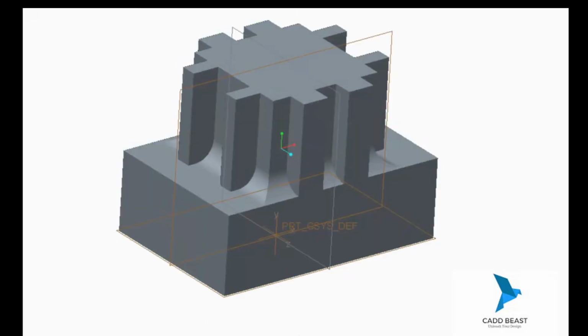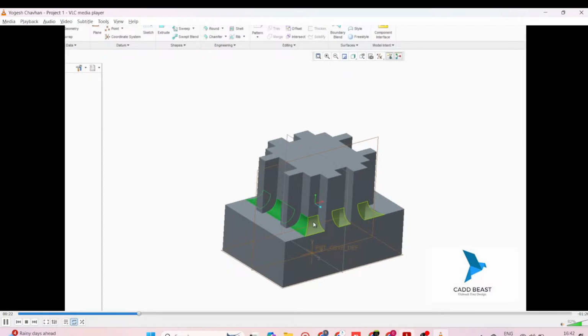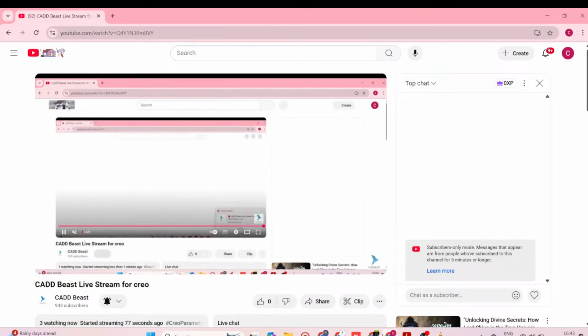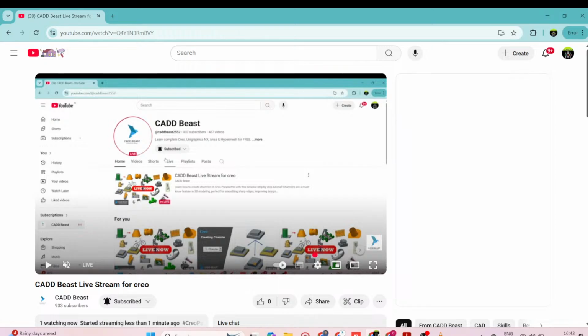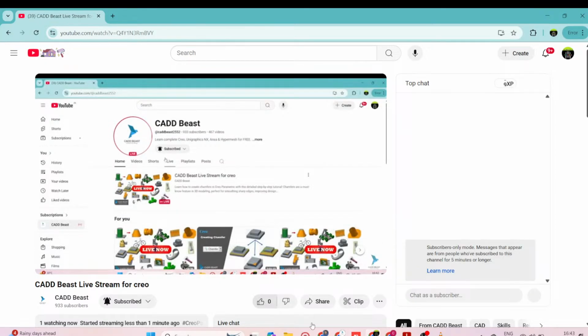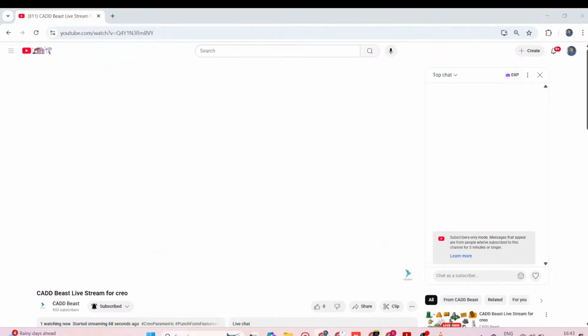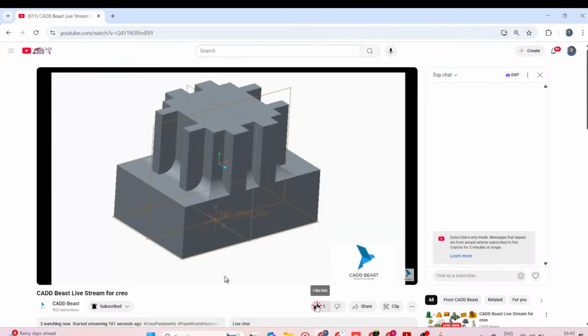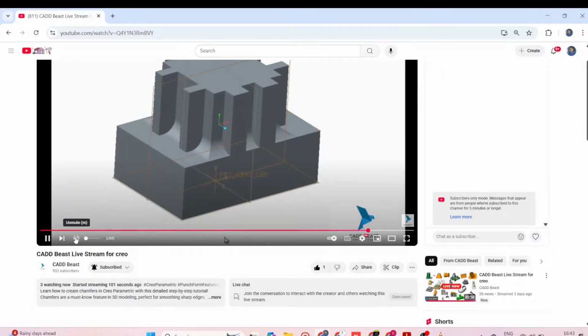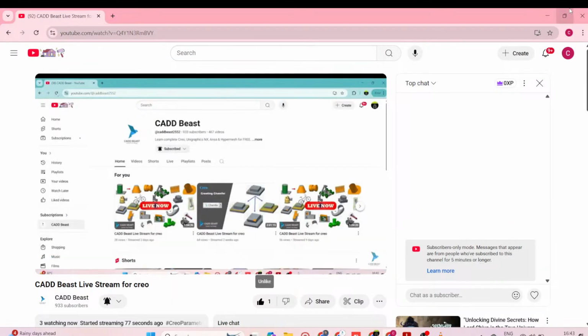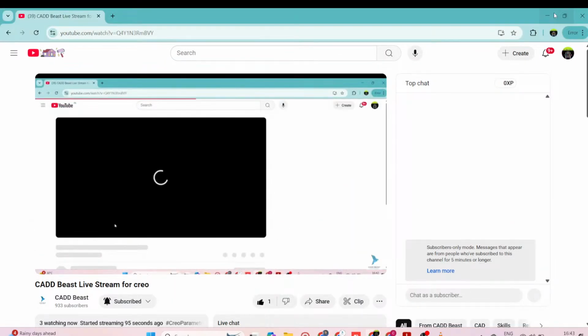The first step is to select all the rounds. Now that all the rounds are selected, I want to click on the Editing tab and then click Remove. As of right now, the Remove feature wants to remove every single part of the rounds, but I want to keep these quarter rounds intact.